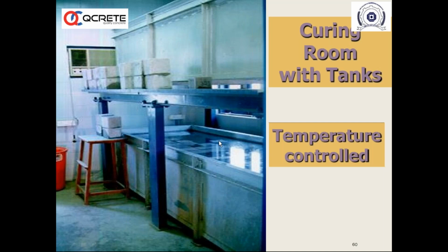Why does it have to be done like this? Because this is a standard. This is a reference actually. If you are purchasing any material, there is a standard procedure to be followed for finding the properties of the material. So as per Indian Standard, 27 plus or minus 2 degrees, we have to cure the concrete. This is the reference. Whether you are in Delhi, Hyderabad, Ooty, Cochin, whichever place you are in, the curing has to take place at 27 plus or minus 2 degrees.